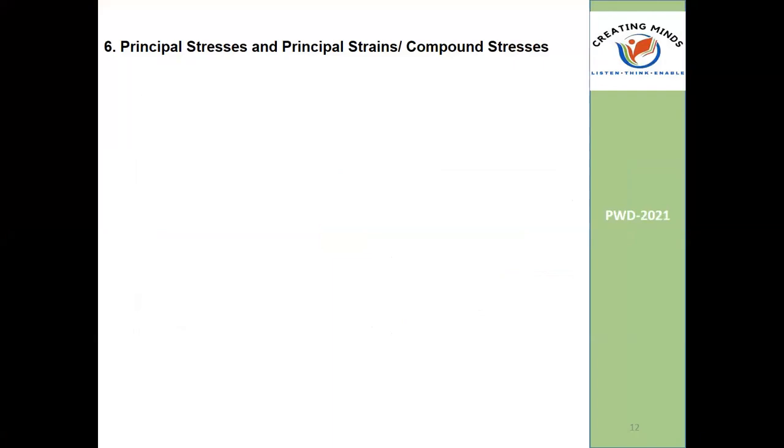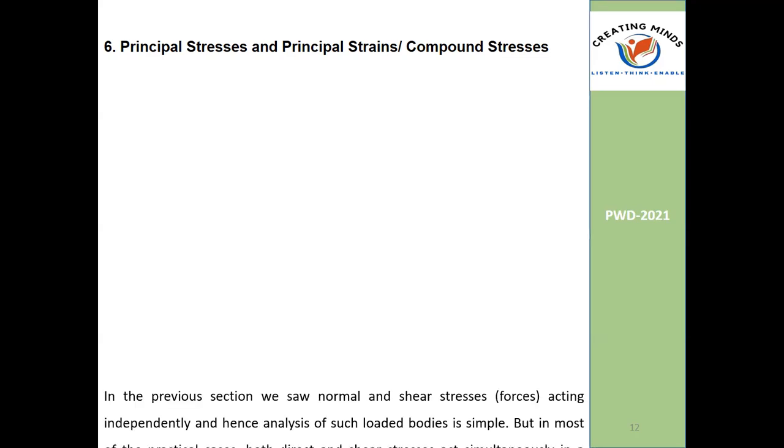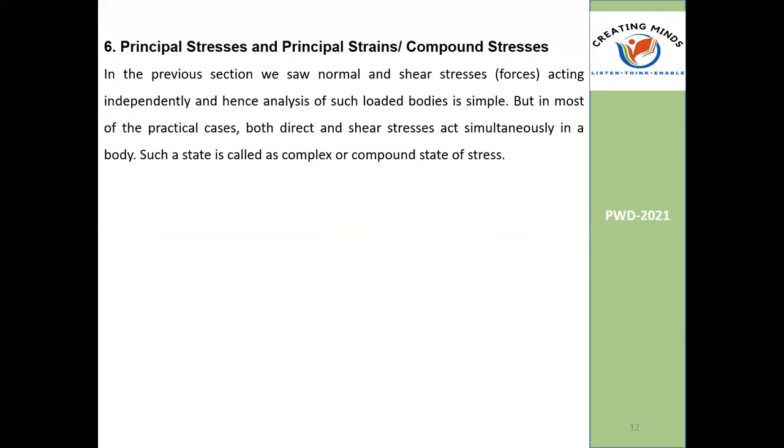Yes, principal stresses, principal planes. So I have just briefed, within the 5-10 minutes, regarding that particular thing. So principal stresses and principal plane. In the previous section, we discussed only the normal stress and shear stress acting independently. That is one dimensional. But in a system, if shear as well as normal stress are acting simultaneously, that is your principal stress, that is a two-dimensional stress system. Okay, so stresses on an inclined plane.